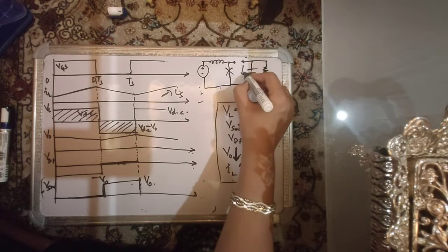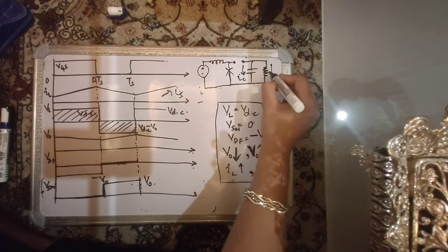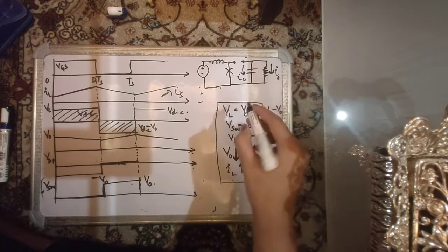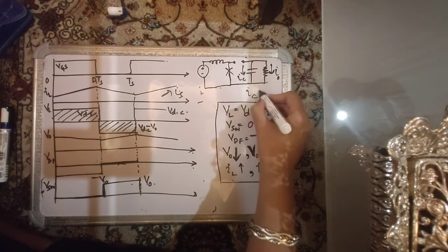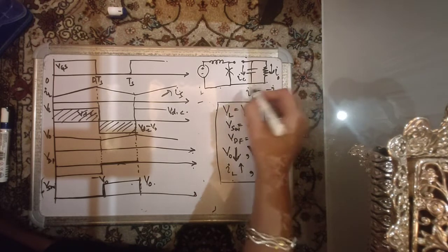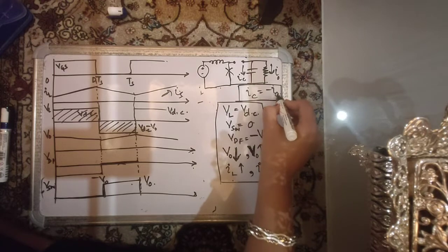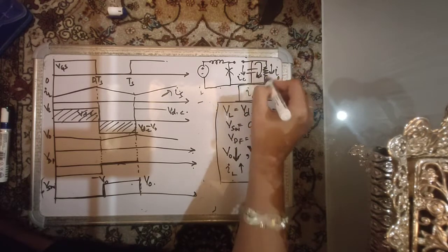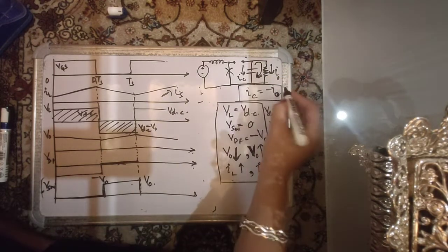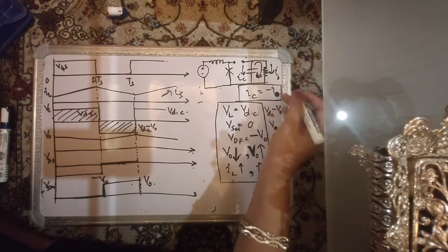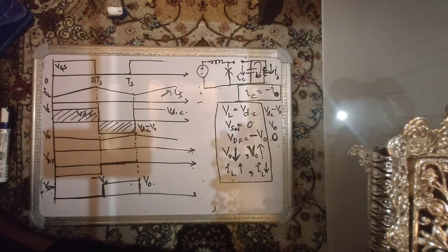And if I have defined IC like this and I naught like this, this time IC is equal to minus I naught. ये माइनस साइन ये भी इंडिकेट कर रहा है that the capacitor is actually discharging, right? I can reverse my conventions completely, but it's generally better to use a convention that denotes minus as discharging. You can very well use plus as discharging, that doesn't change anything.